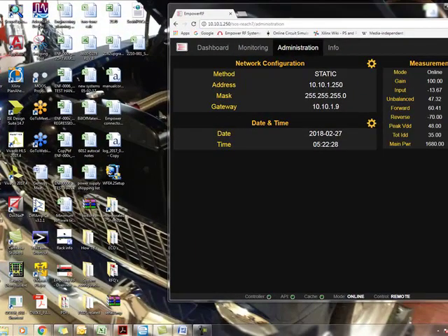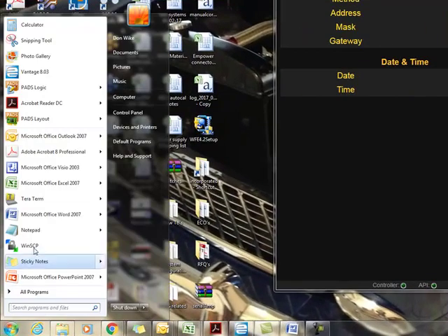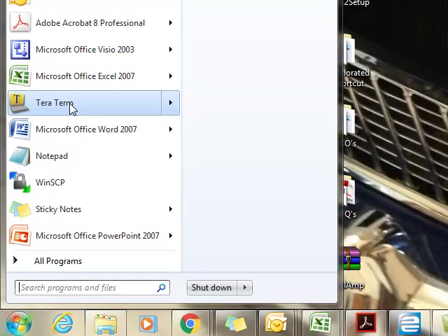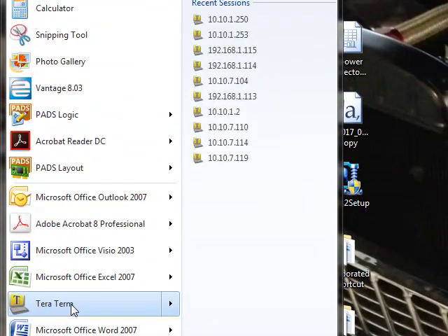And the next step would be to open up a TerraTerm application. This is allowing console to be able to send the M2M commands to the target device. In this case, we choose TerraTerm as it's one of the common applications that we use in-house at M-Power, but there are many other terminal applications that are compatible, as well as you can develop your own host application.